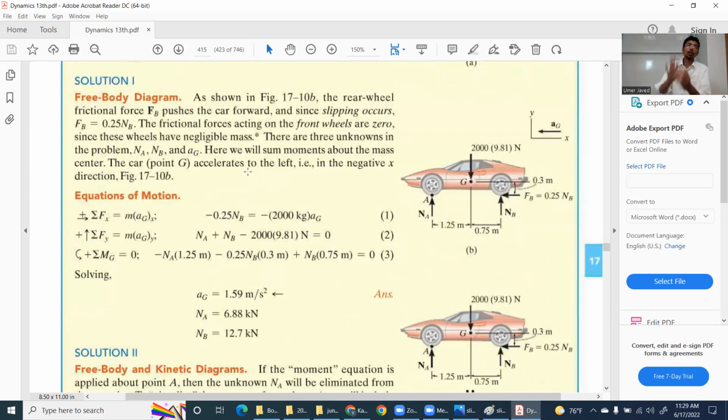So when you talk about summation of moment about any point on the object, let's say point A, focus on point A. Now you have to write summation of moment about point A, okay, relax, it is equal to IG alpha plus MAGD. Is the center of mass rotating? No. So IG alpha will vanish and you will have MAGD. Again, 80% of the class last time also forgot this, so I'm trying to emphasize.